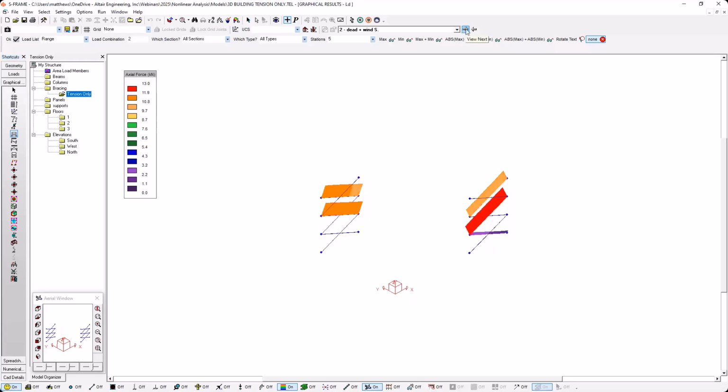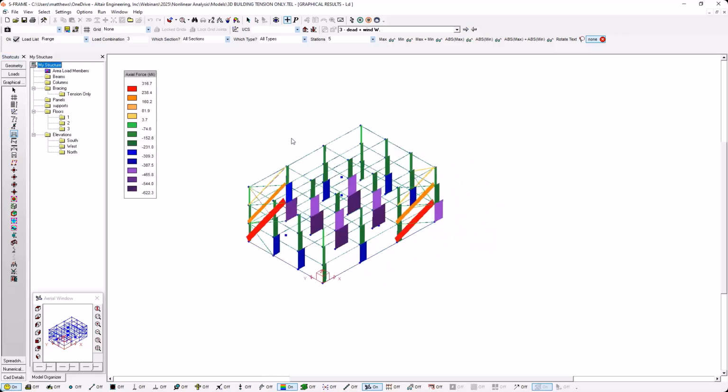And I can see for different load cases or combinations, we might get a different distribution of members that are in compression or tension. So imagine doing this manually would be a very time-consuming and finicky process, but the solver here can do it for us automatically. And if you get a large structure with different loading mechanisms and so on, it's not really feasible to do this manually with a linear static analysis. It's going to require you to basically update for every single load condition, and it would require a lot of manual effort just to approximate the behavior.